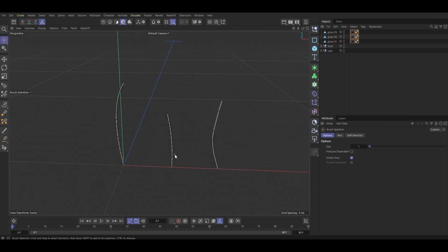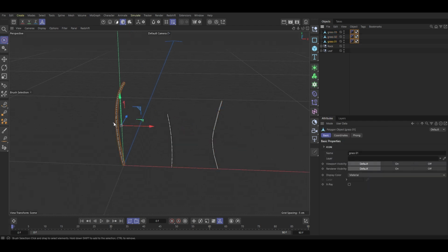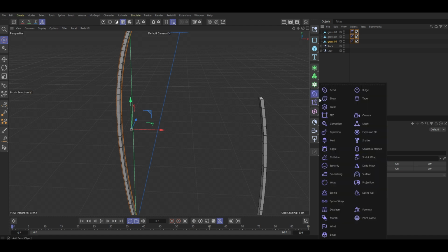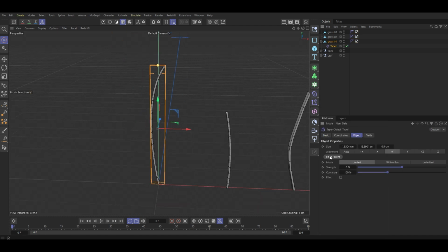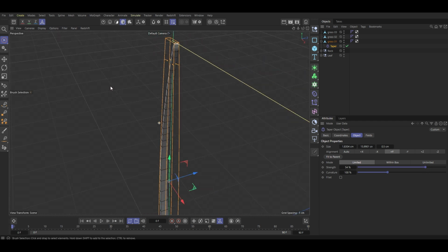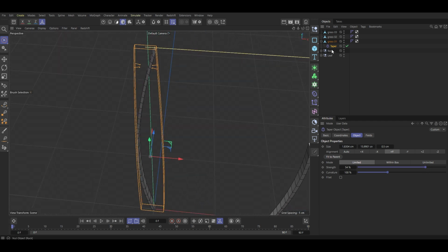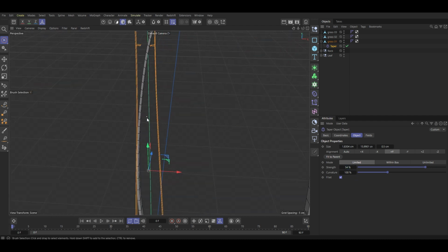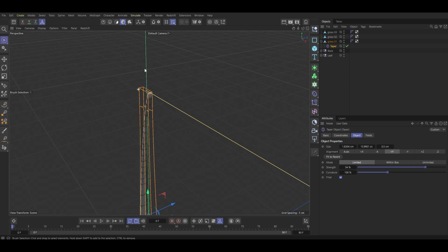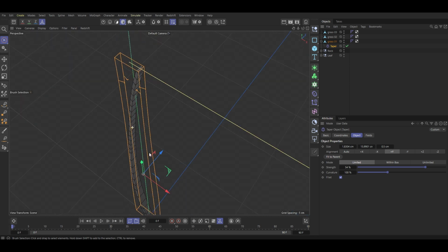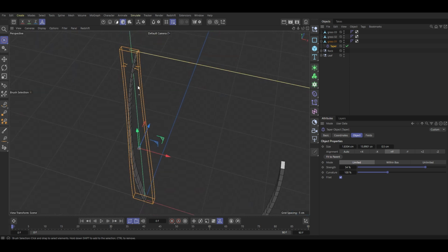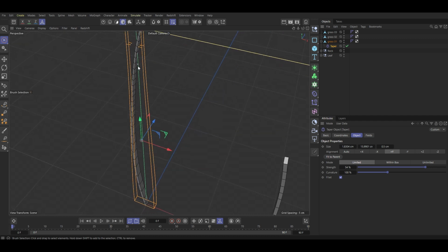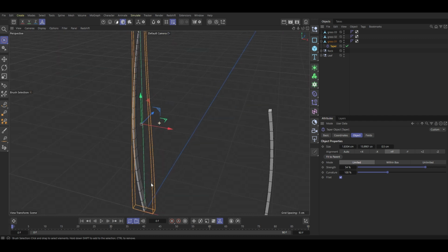Okay, nice. So here what I can also do is use a taper to make the top. Let me see if I'm correct. Yeah, let's use the taper and make this one fillet, just adding some form from the top, making it a little smaller compared to the bottom.